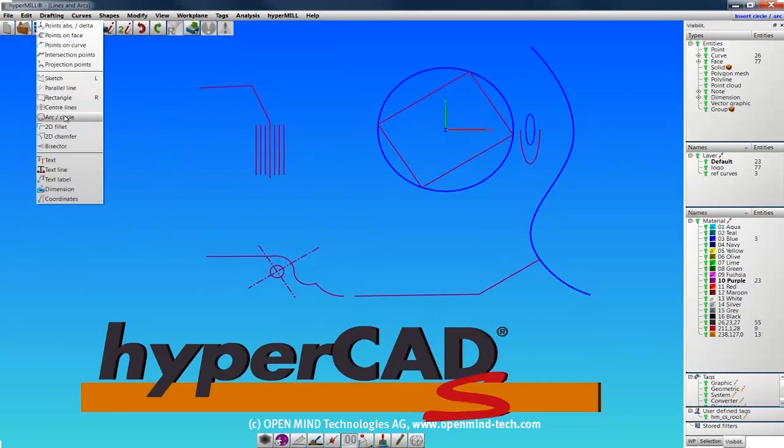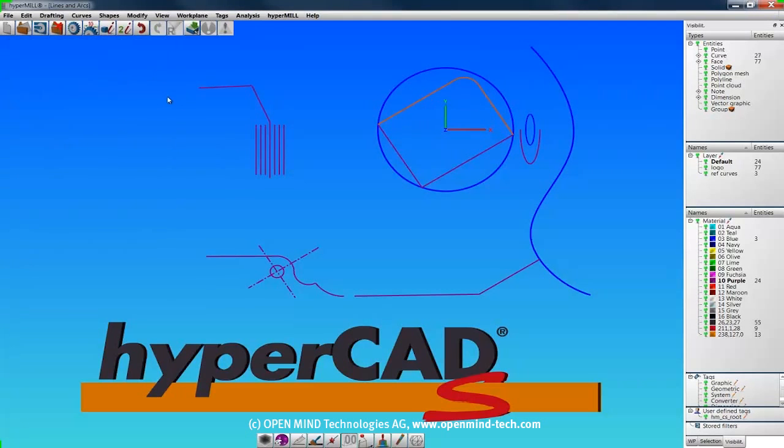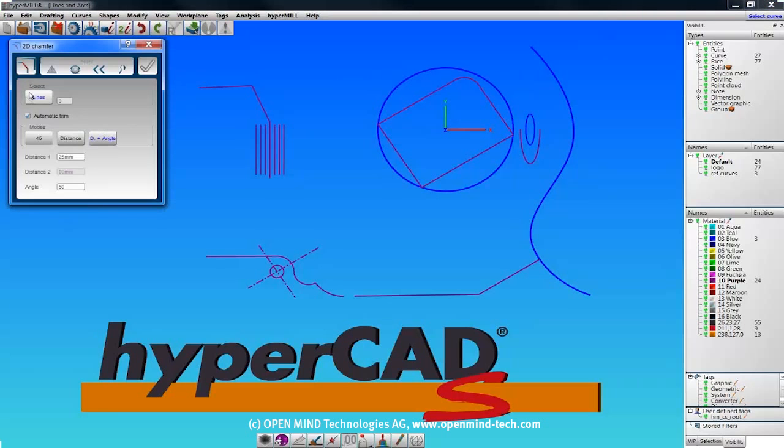The 2D fillet command is very simple. You select the curves, specify the radius either dynamically or directly, check whether you want the curves trimmed or not, and execute. The 2D chamfer command is similar, but has modes for 45 degrees at a specific distance, 2 different distances, or a distance at an angle.